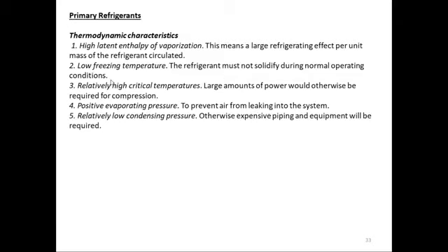As you know, in your refrigerator, the temperature can go as low as minus 25 degrees centigrade. So your refrigerant must be capable of not freezing at that temperature. So the freezing point should be much lower than that.